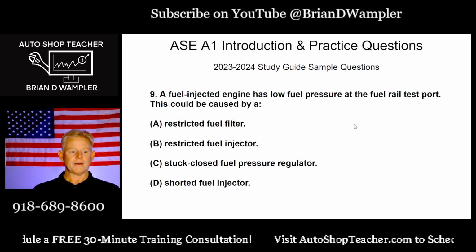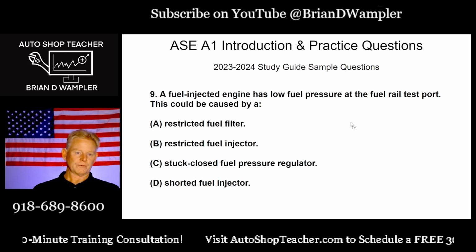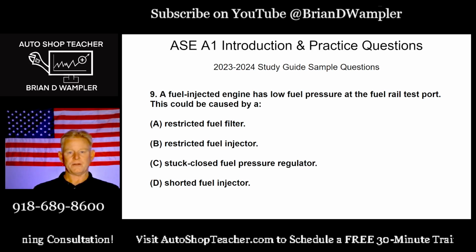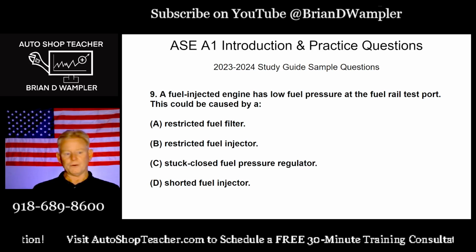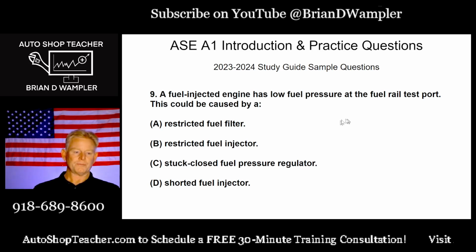So we're going to look into that. And then a shorted fuel injector. Shorted, we're now using electrical terms, okay? Shorted fuel injector. I can tell you, I'll just go ahead and let that one out. That's going to cause possibly the injector on an electromechanical hydraulic type injector to not open, okay? Or if one circuit's shorted to ground, then maybe to never close if the power's applied.